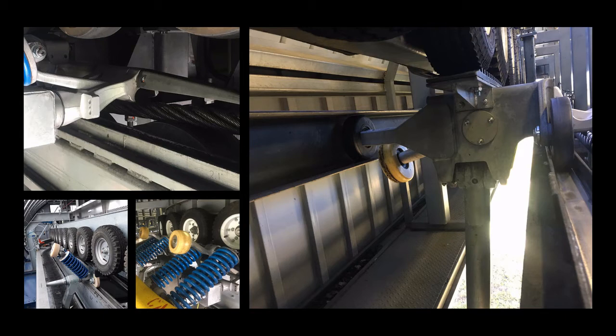The other images on this page all show different types of grips passing through the terminals via tire banks. The tire banks provide the motion for the grip when it is not connected to the haul rope. Power is transmitted from the tire banks to the grip through the traction plate. These tires can either be pneumatic and filled with air or solid rubber.